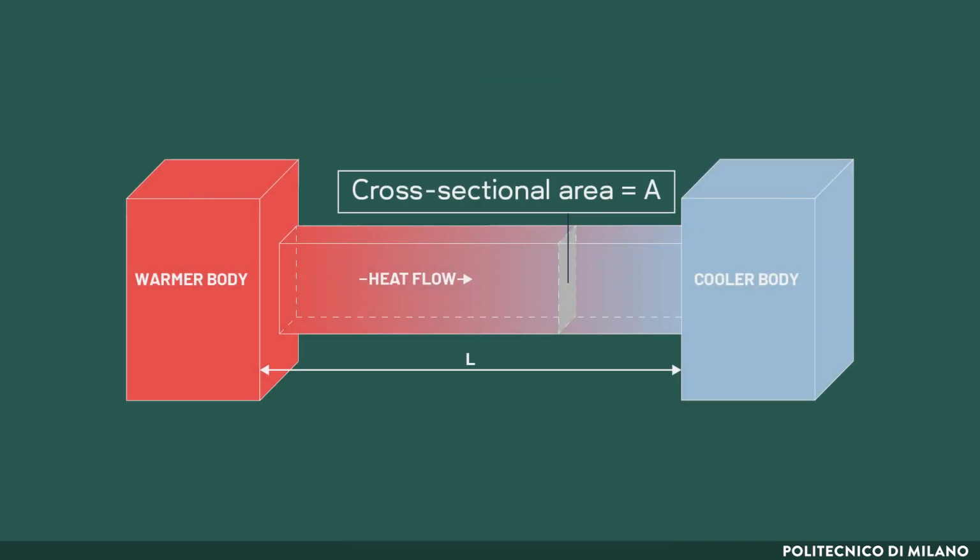In conduction, when a solid body is heated, the heat is transmitted from one end to the other. The atoms of the warmer part of the body transmit their greater thermal agitation to those adjacent to them, and the body progressively increases its temperature. When the body is heated continuously from one part and has reached the steady state, the temperature gradient through it is linear, as in the case of a homogeneous wall.